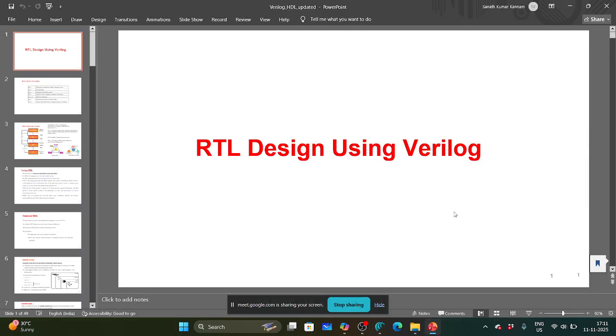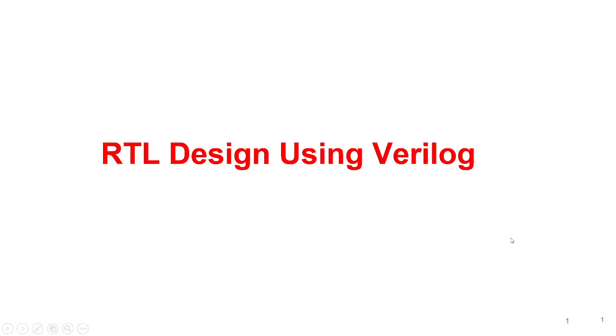Yes. Okay. So today we'll start RTL design by using Verilog. RTL, as I told you last class, is Register Transfer Level design. This shows how the data is transmitting through the registers inside when it is converted into hardware. It looks like flops. So how the data is transmitting through the registers, that is nothing but RTL design.